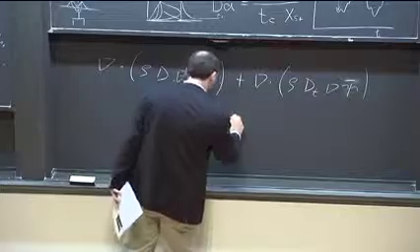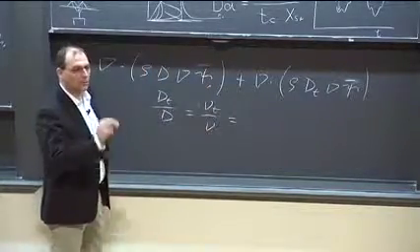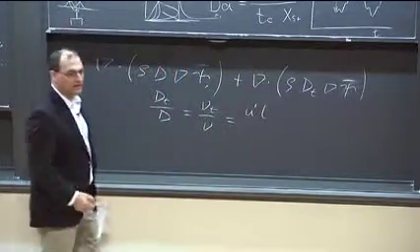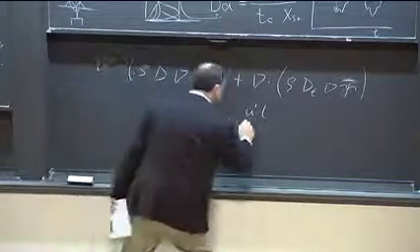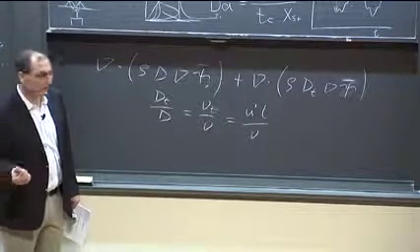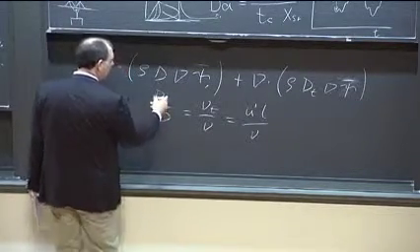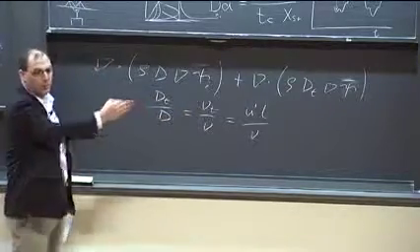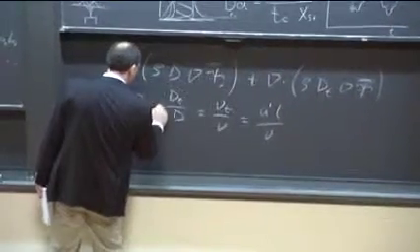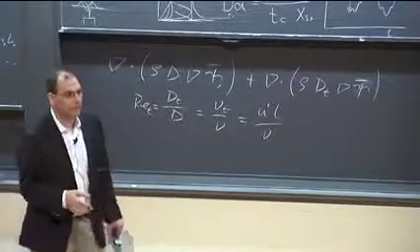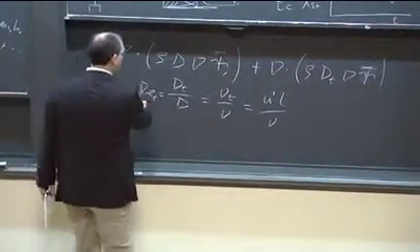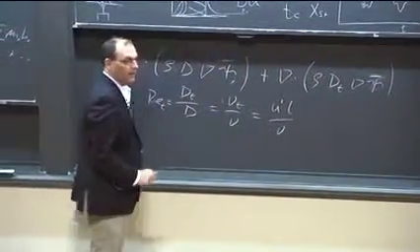Now, I said earlier, how do we model this nu T? I said we model this as u prime times L, the integral length scale. Okay? So if I do this, what do I have? It's a Reynolds number. This is the turbulent Reynolds number. So here I assume, from here to here, I just assume the Schmidt numbers are 1. Okay? So this here then is the turbulent Reynolds number. Turns out in a turbulent flow, this is at least 100, let's say. Okay? Which shows you that as soon as the flow is turbulent, this term is at least 100 times larger.